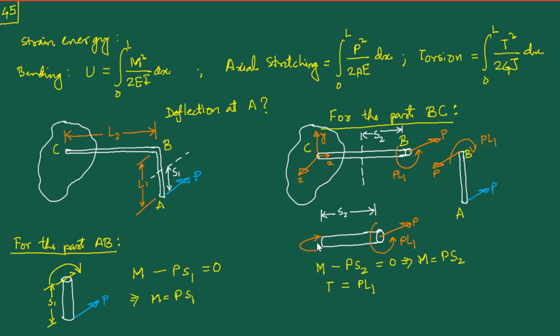So if you draw that, the shear force V is going to be equal to minus P, and you can actually draw a compensating torsion here, but I will refrain from doing that because it has already cluttered up the picture. So this is our T, and we have the V also. This V is going to be equal to minus P, but we won't need it anyway.